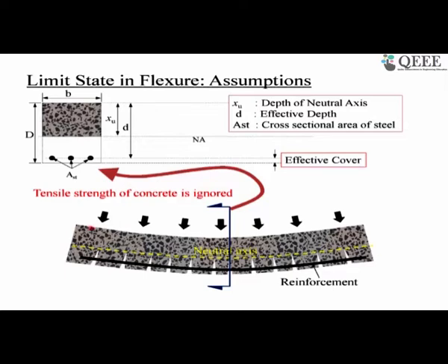Okay, you have already seen this figure at the beginning of the presentation. This is subjected to transverse load, and this yellow dotted line is the neutral axis. So the portion above is under compression, and this portion is under tension. When it is subjected to tension, cracks develop at the tension face, because concrete cannot take tension, and this tension will be taken by the steel. Now if I take a section here, this is the neutral axis. Above the neutral axis we have concrete which takes the compression, and below the neutral axis there is no concrete, because the concrete cannot take tension.